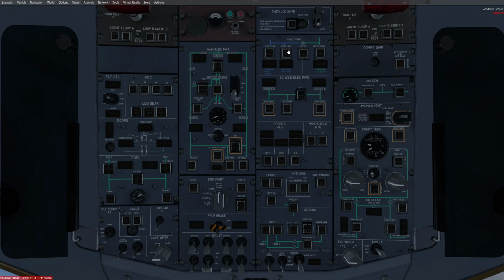So anyway, the auxiliary pump is really a good one at the start, and we'll see there's another button below the parking brake too that's useful for hotel mode, which gives the aircraft power like a GPU normally would, but you're going to fire up the right engine. Don't let the prop turn using the prop brake, and then that'll be your electrical source after that. We'll do that too here in a minute.